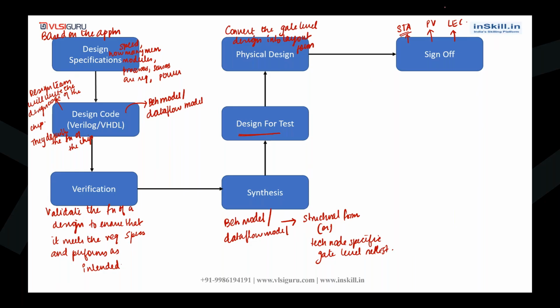And then we have the physical verification PV. It is actually to verify the layout of the circuits. And then we have logical equivalence check LEC. Okay. So LEC is actually done to check whether the final design is logically equivalent to the original design or not.